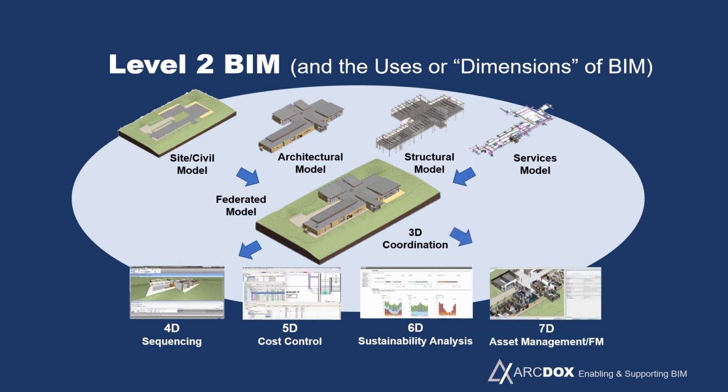And the last part is, since we have this data-rich digital model during construction, we can also populate that model with additional information that will be useful to the property and facility managers, such as warranties and maintenance periods, etc. So that sort of asset information model is what people are calling 7D BIM. So it's important that you know what these terms mean when people are talking about them. When you're in meetings as a project manager, you're probably not going to be doing these things, so these will be done by other people, but at least you should know what they're talking about.